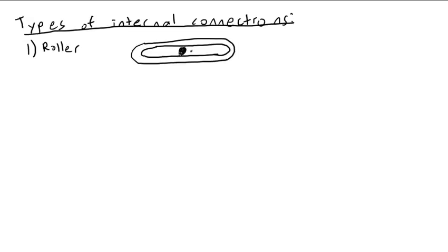And the other member is joined to this like here. What this means is that this can transmit an internal force only in one direction, the direction perpendicular to the slot. See, if it tries to transmit a force in this direction, the pin is just going to roll. So I would call this an internal roller connection.